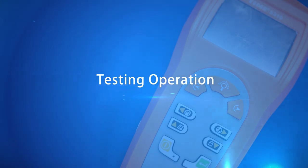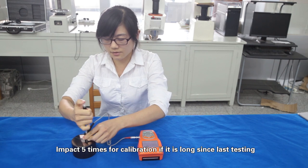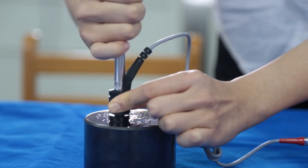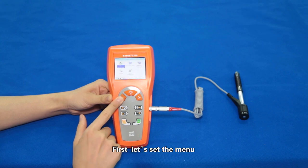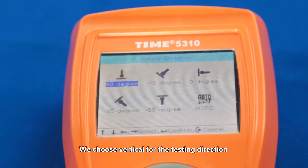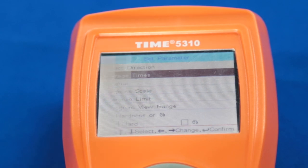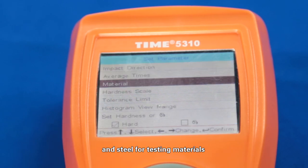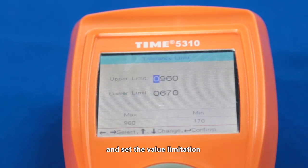Testing operation. Impact 5 times for calibration if it is long since the last testing. Switch on, then let's test away. First, let's set the menu. We choose vertical for the testing direction, 3 testing results to calculate the average value, and steel for testing materials. We can also select other hardness scales and set the value limitation.